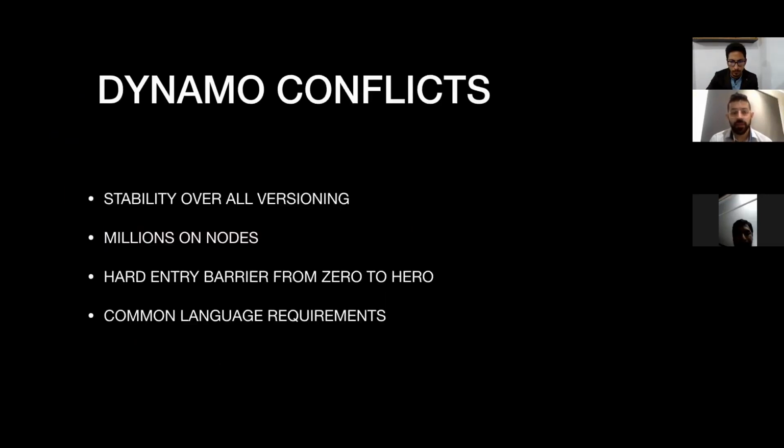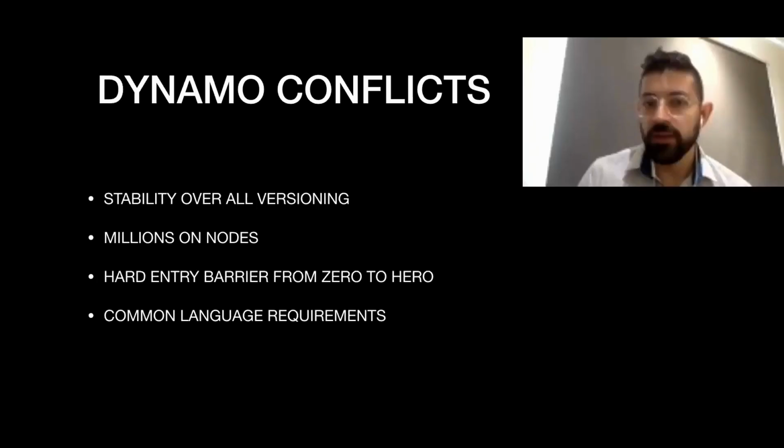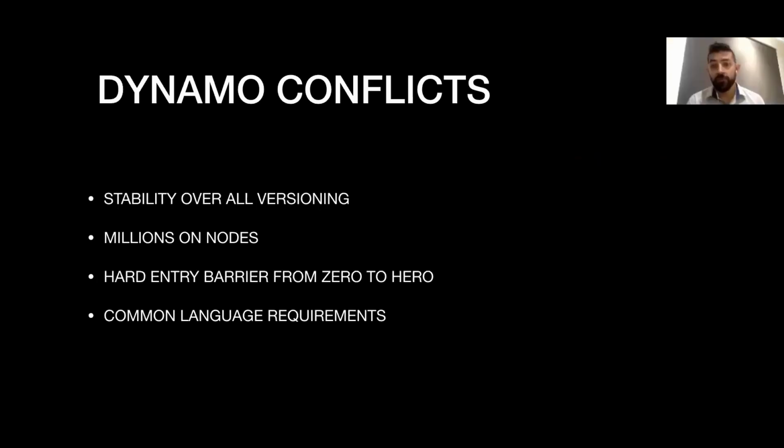Then what would be the Dynamo conflicts? Not everything is sweet as it sounds. There's a lot of things about versioning because it's going 2020. You also have the Dynamo version that it's going 2.0, that you also have the versions of the nodes, and depending on the developer, if they haven't updated their database, there may be some issues. So you need to be aware of how they work. So you can get lost and feel overwhelmed of all that content, but don't get too scared. Just Google it, change it, check, and that will help you enhance your working pattern.